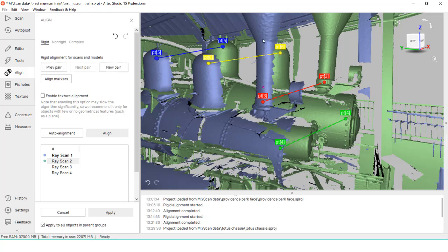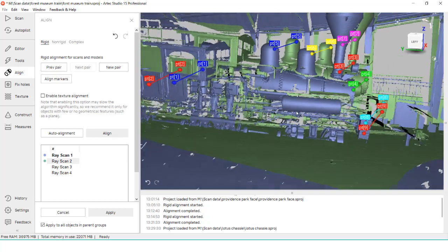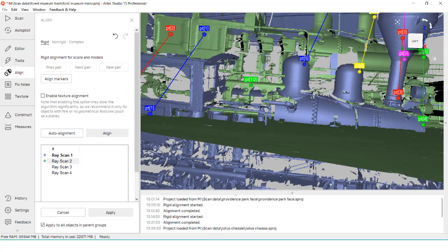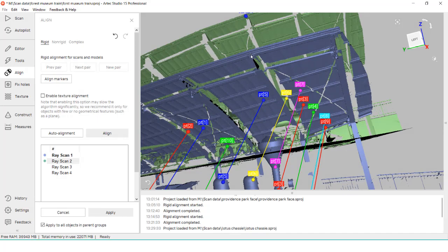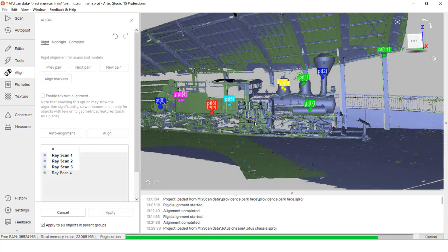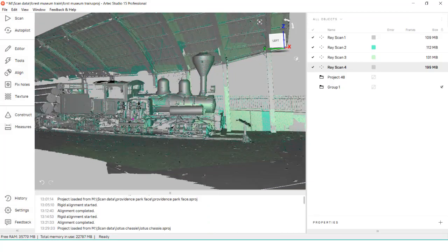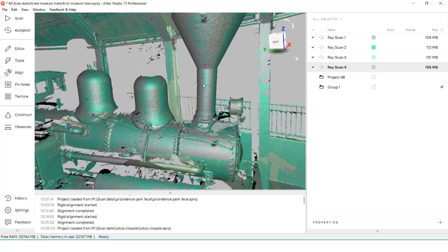This may be corrected within the global registration tool, but we want to get the scans as close as possible within the Align step to ensure that the registration does work well. If the registration fails, you can always undo it and select more points, or even reposition the scan in a better way to make the alignment snap together easier. After an alignment, I typically double-click the scan's name again inside of our list to unregister it. This lets me see how well the two scans blend together. We're looking for a very sandy surface with the two scans overlaid with one another.